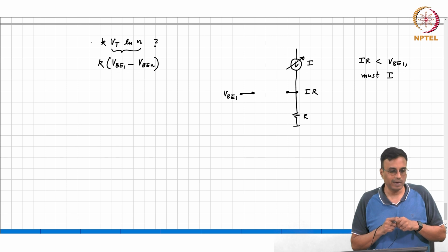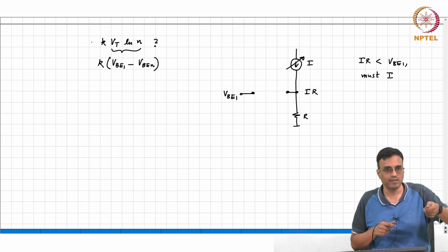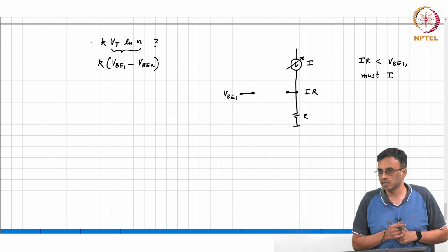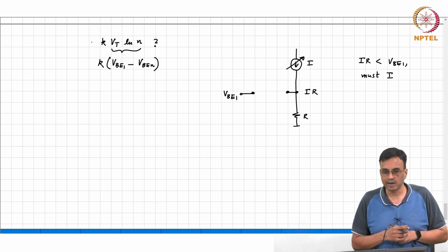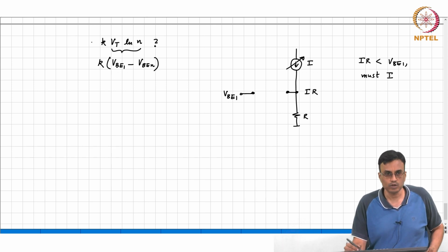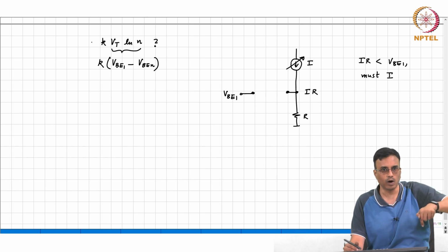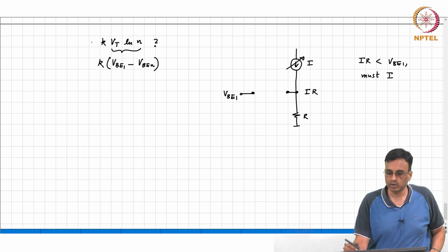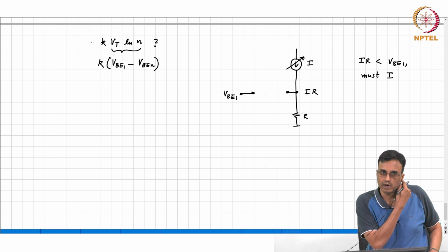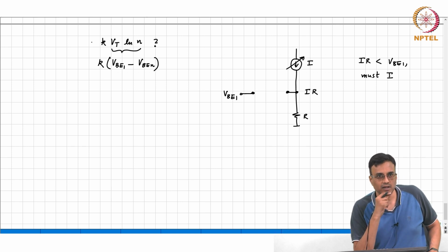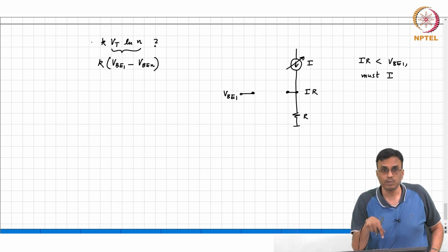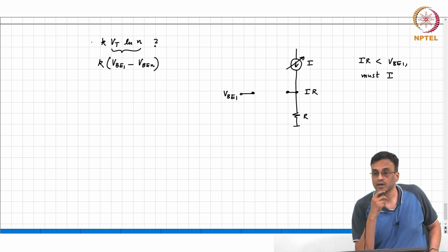Okay. So now, of course, you can't keep sending a technician every time you want to convert a voltage into a current. Whatever you can do, the moment you describe it clearly, you can get an electronic circuit to do it, correct? So this current source, this current is pushing down and it's variable. Can you think of some device that you already are aware of, which can push current and you have control over that current? You need a current to be pushed down. PMOS.